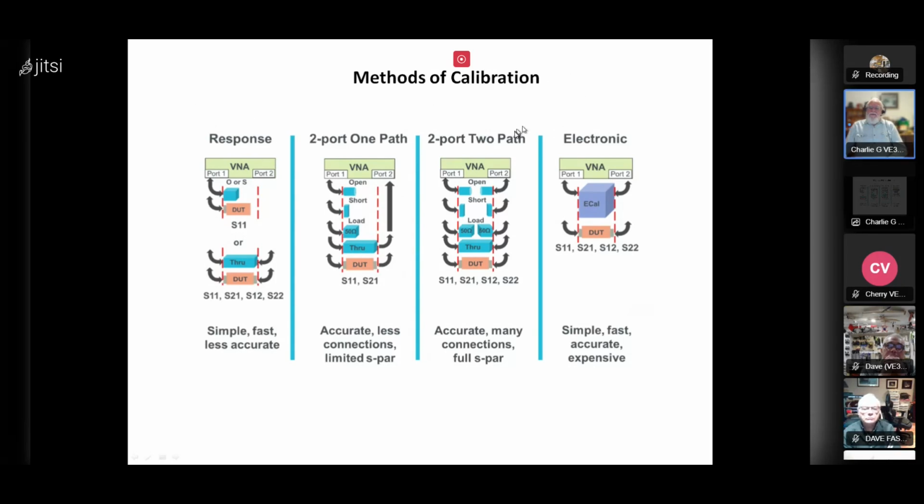So the third type, if you've got a VNA which is capable of doing measurements, you know, the 1-1, the 1-2, the 2-1, the 2-2 type measurements, you would need to do those opens and shorts against each of the ports. This is not really applicable to the NanoVNA because it only has a single signal source.